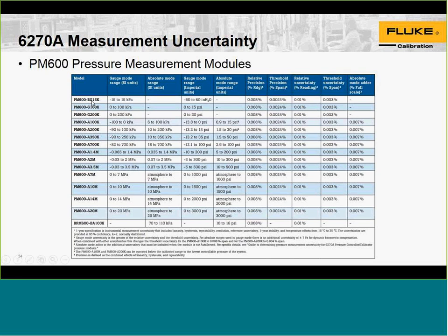It's bidirectional gauge, which is the G, gauge, or absolute, which is an A in the model of the range. And I would like to add also that for the absolute best performance for those low draft ranges, we offer a special version of the 7250 line controller. It uses the quartz Bourdon tube for very good performance at the very low pressures, for the ultimate performance at the draft pressure. It also has extremely good control down there.